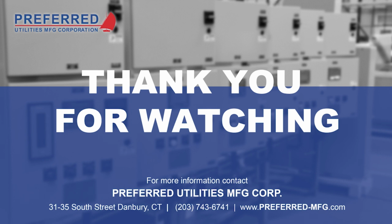And then they explained to me what you just explained, that the scanner is looking for flicker, and if it gets too much signal, it just doesn't see any flicker, and it thinks it's seeing hot refractory, right? And it's programmed to shut you down. Exactly. And like I say, that's one of the issues that, quite honestly, is most of the time solved fairly easily. But I've actually done it in my past, not only on the standard like UV or IR scanners, but I've even done it on the more expensive and elaborate smart scanners. Sometimes the simplest solution actually will work.